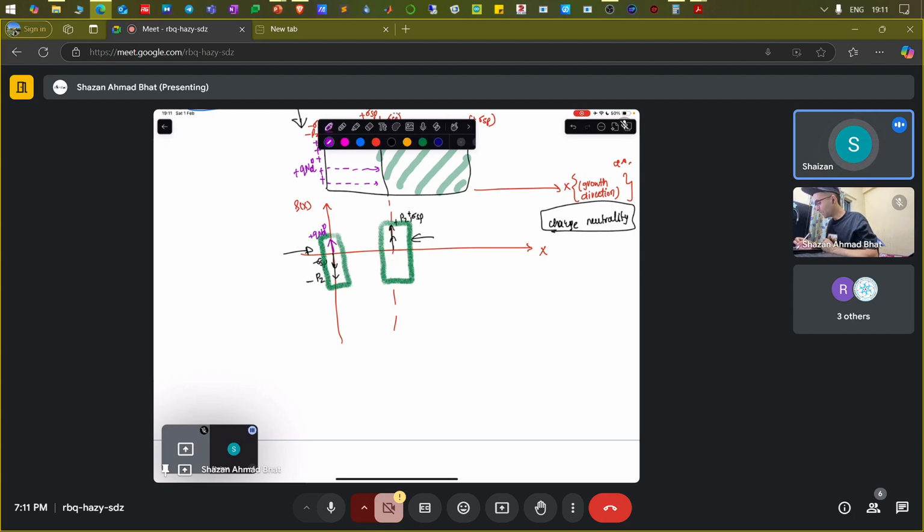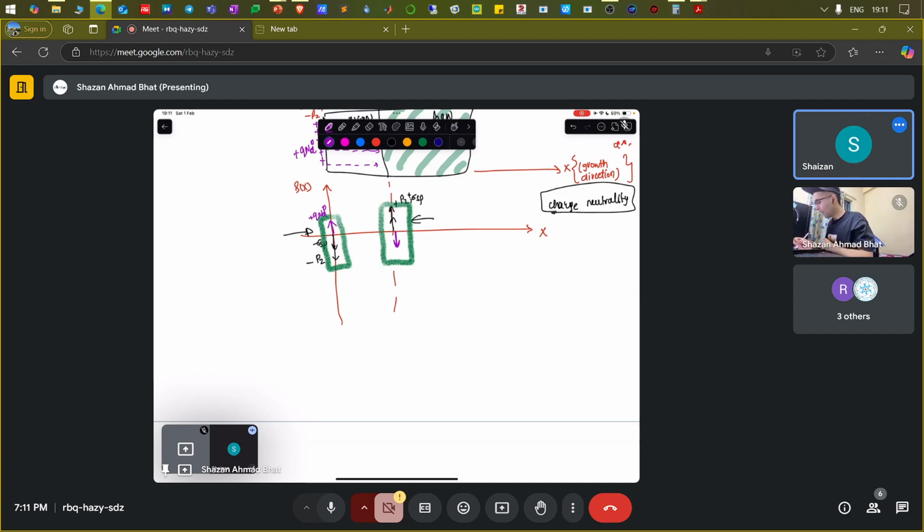And this negative charge is basically those electrons. Why I draw it slightly inwards towards the GaN, it has a certain reason. And where does this negative charge come from? That is the same electrons which come from surface states and go here, settling at this particular position. Why does it settle at this particular position? Because that is where the positive charges are present. Okay, so now the charge neutrality is maintained. The charge on this side is equal to the charge on that side. You have the neutral condition.